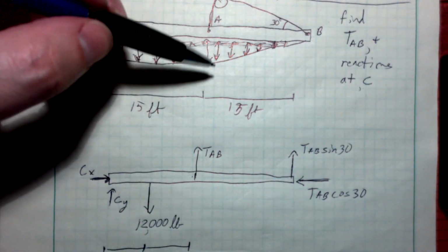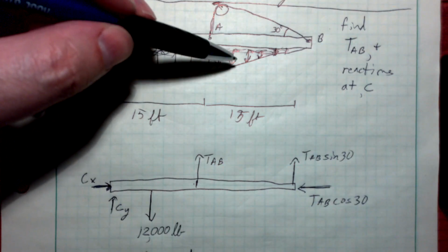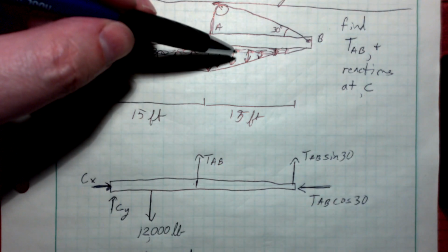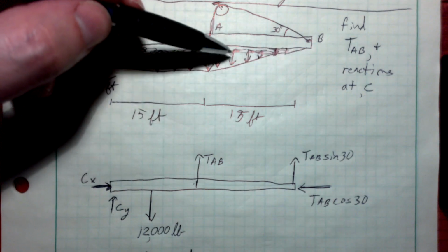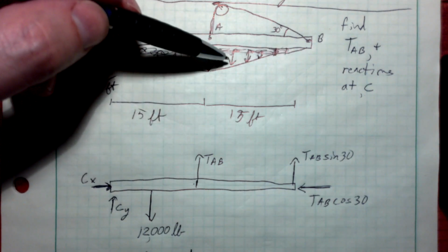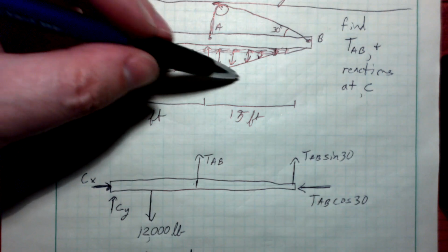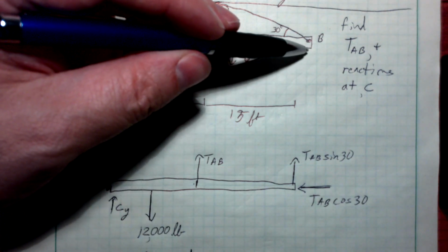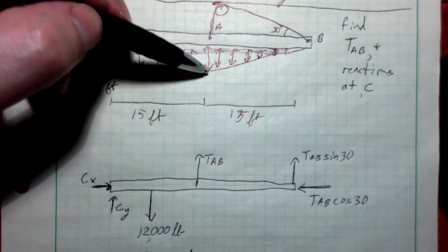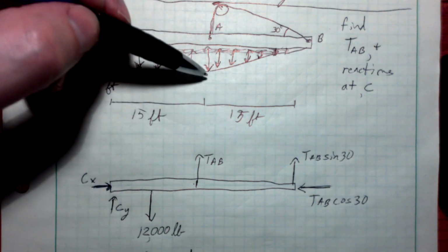Where do I put it? Well, it's going to be right here in the thickest part of it. Basically, the center of the triangle is not halfway in between because it's not equal down here. I've got more weight, so to speak, right here. And remember, we talked about last time, it's 1/3 of the length from the thickest end, or 2/3 of the length from this zero end. Well, so if I go 1/3 of this 15-foot span, 1/3 of 15 is 5.